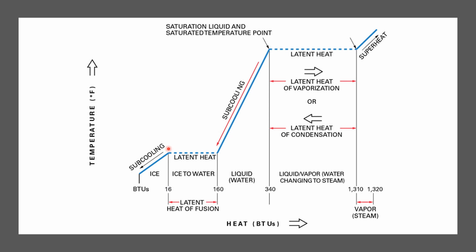What we're saying is that we start melting this block of ice continually by adding more and more heat, but at this point over here where we're not quite fully changed into liquid water, we are still at 32 degrees Fahrenheit. And I know that's a hard concept to imagine. We start here at 32 degrees Fahrenheit, we add heat, so automatically we would assume that we have more heat over here, or a higher temperature. But this is a latent change, and we cannot perform sensible heat change when there is a latent change going on in the system. So here is 32 degrees, here is 32 degrees.